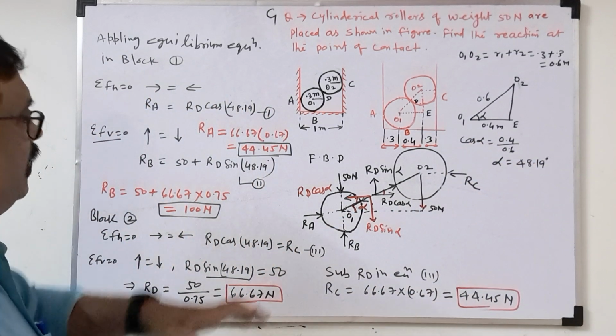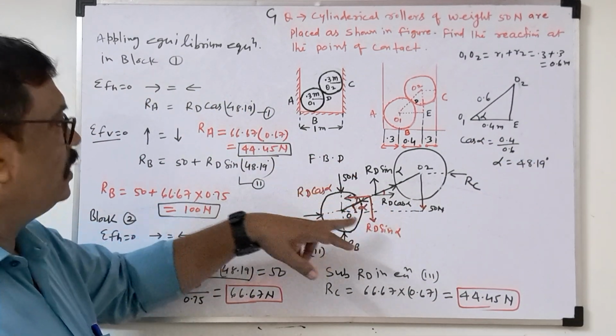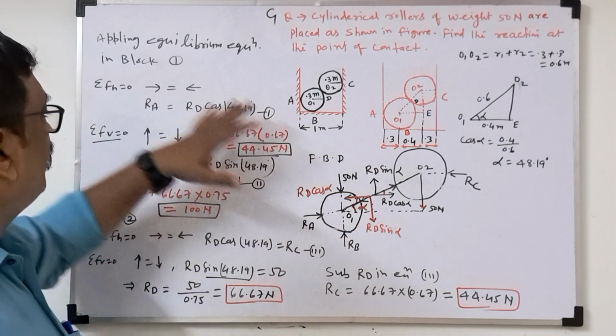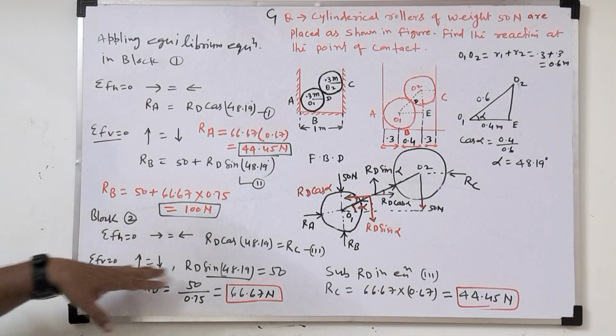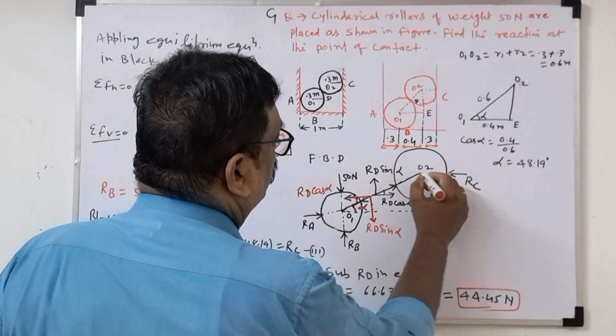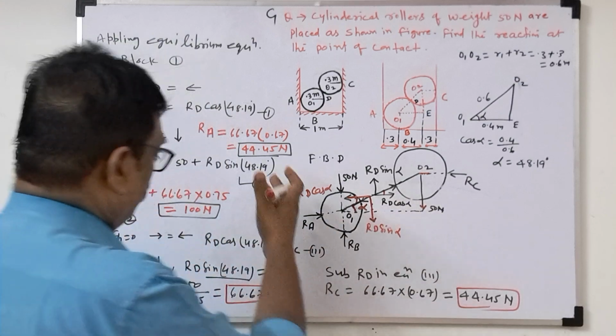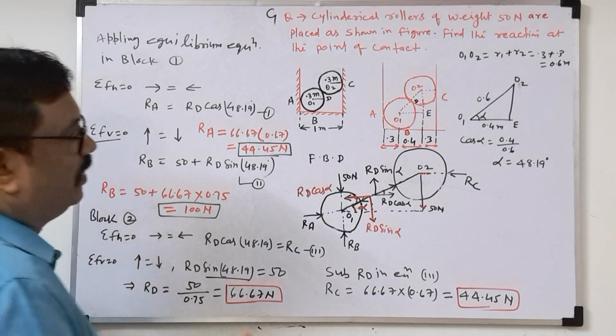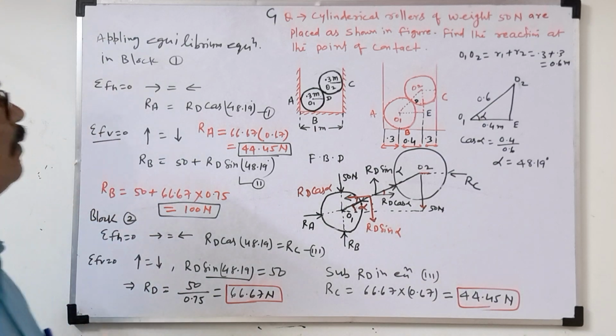Once we get the angle, resolve this part. Where there is a contact point, reactions will act, and applying the two equilibrium equations we can get the answer. At this point we could apply Lami's theorem, since two forces are there, but it's not required, as one resistance force is already going, so we get the same method. Okay, so this way we can solve the problems.